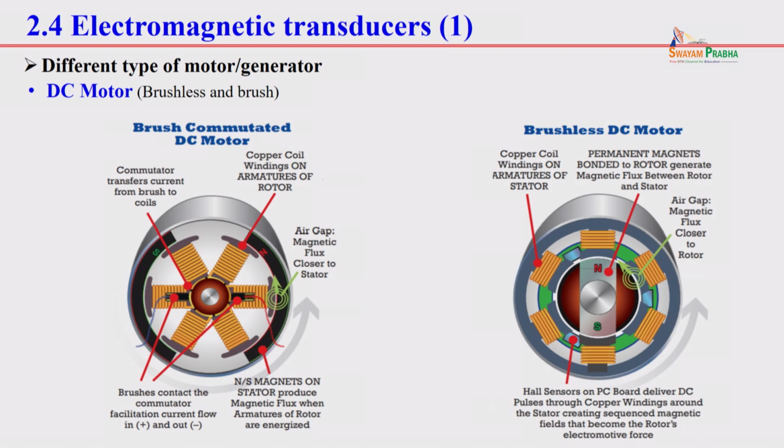And when we design a wave energy converter, a lot of time you buy a DC motor directly. DC motor has some problems. The brush wears out, right? So in the ocean, it's hard to maintain, and an AC motor will be better. And another thing is, sometimes people say, okay, how about I buy a brushless DC motor? I don't have a brush. Does it work as a DC generator or not?